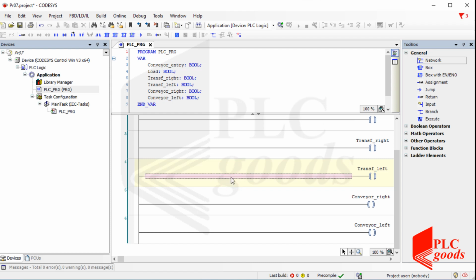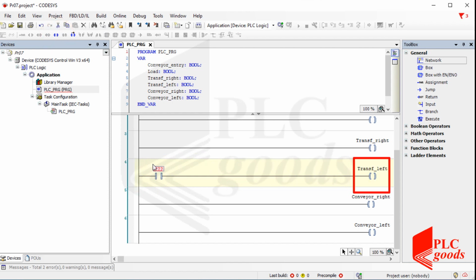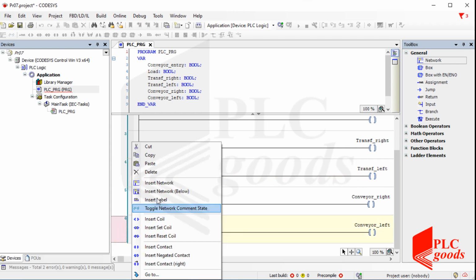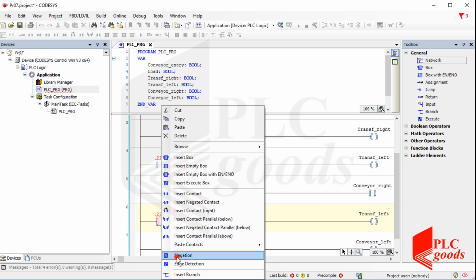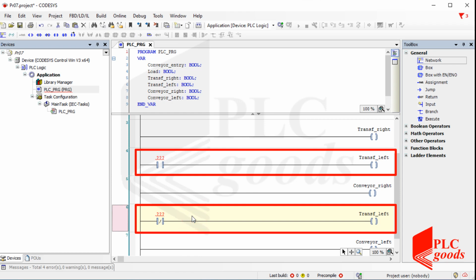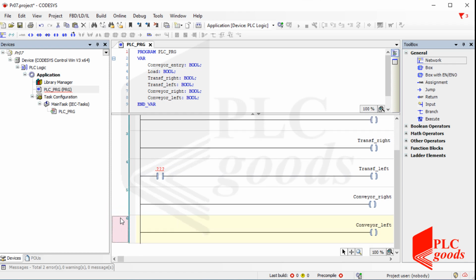A simple way to programming is determining all conditions that turn on an output, otherwise, the selected output will be off automatically. As you know, PLC executes the whole program and then updates all outputs. Therefore, if two different programs are written for one output, PLC will work based on the second one. So, try to use one coil for each output.